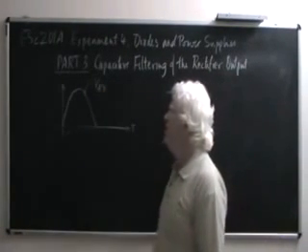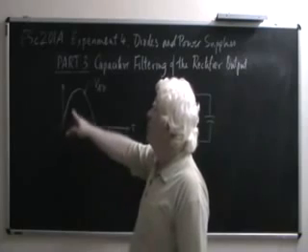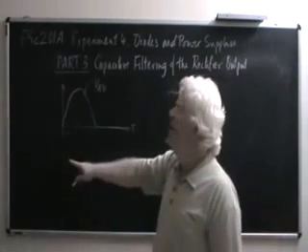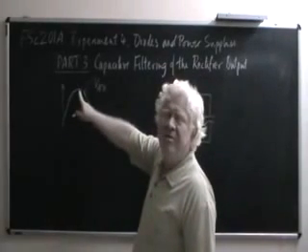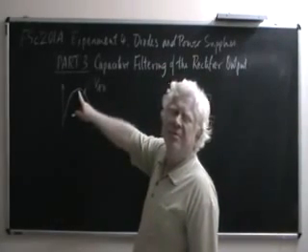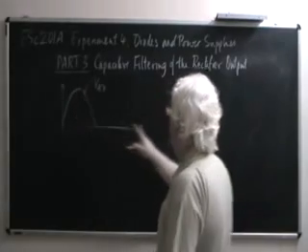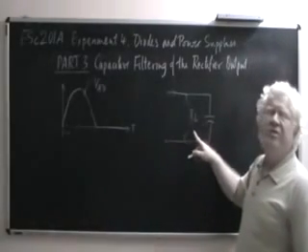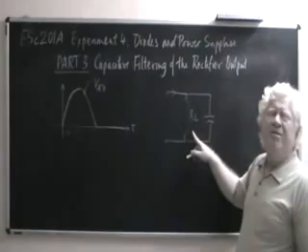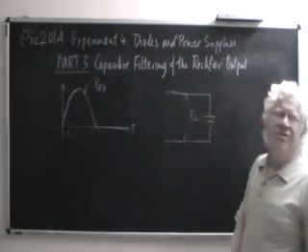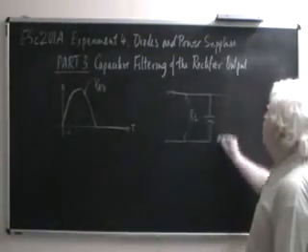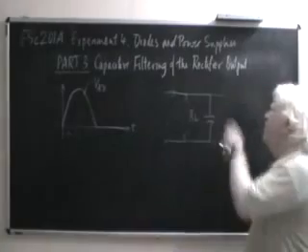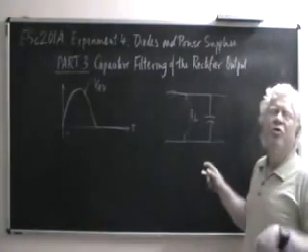In the first quarter cycle, as the rectifier output voltage rises, the capacitor voltage will rise side by side with it. It will reach its peak value at this point, and after that something interesting happens. The capacitor, having been charged up to this point, and with the load resistance removed, has no means of discharging. So the voltage across these two terminals remains at the peak value because the capacitor has no way to discharge.